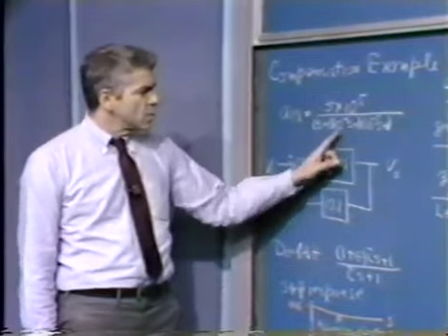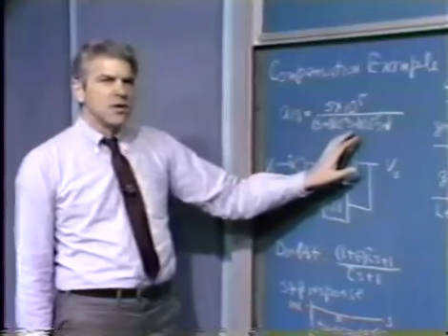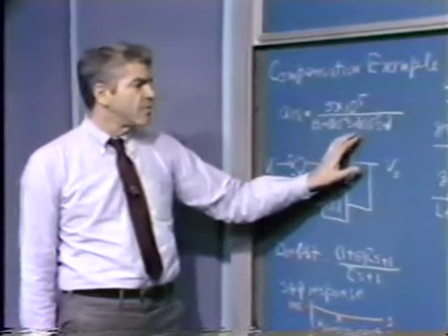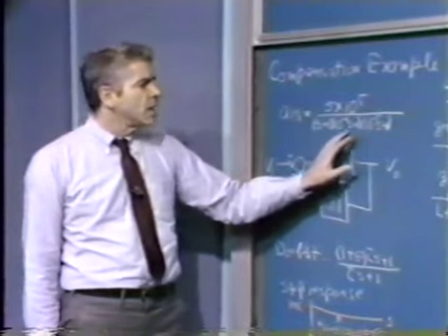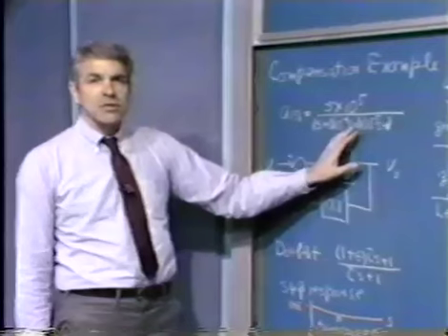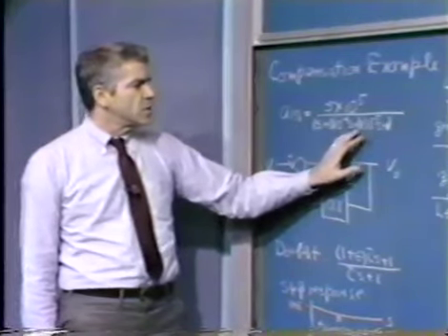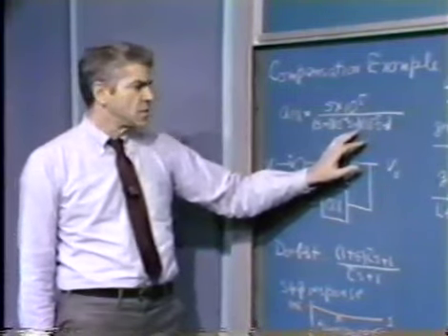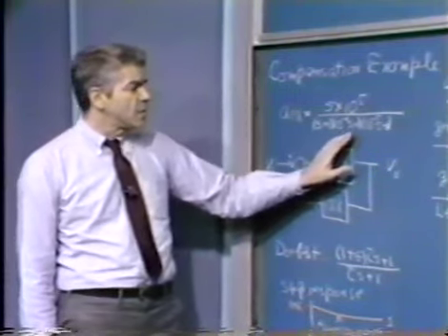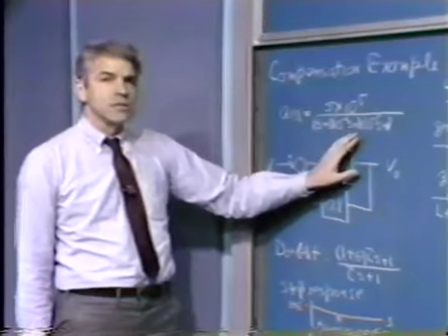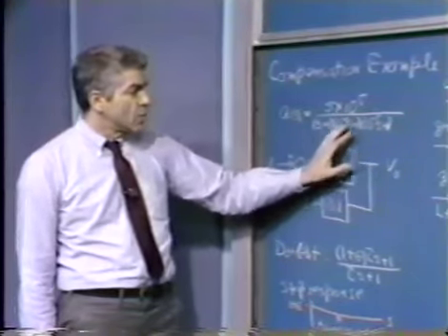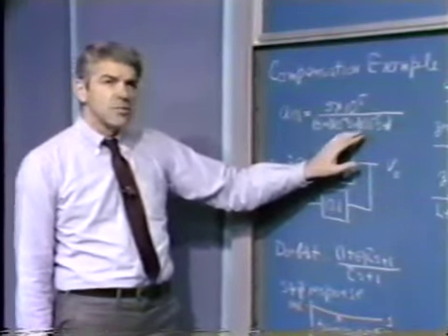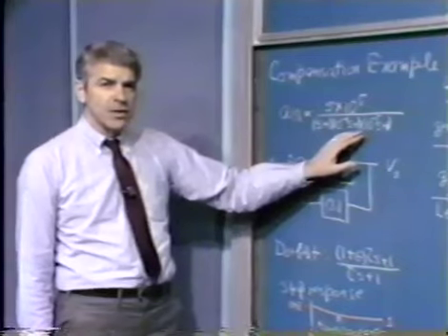The reason we do it this way is that we make sort of a pseudo operational amplifier using several others so that we can control the transfer function very well. And in order to be able to do that, we'd like to have the important dynamics of our pseudo amplifier occur at frequencies well below the ultimate limitations of the components we use to build the system. So in order to be able to build a demonstration system that very accurately represents this equation, I've chosen to limit, or to locate, the higher frequency poles at a frequency that's considerably below the ultimate performance capabilities of modern operational amplifiers.